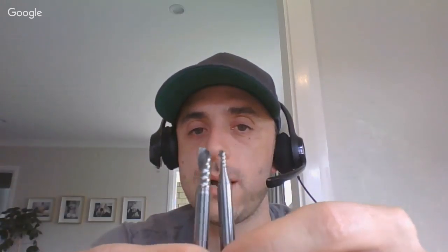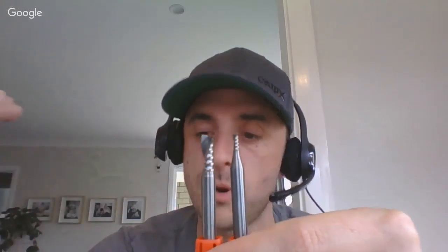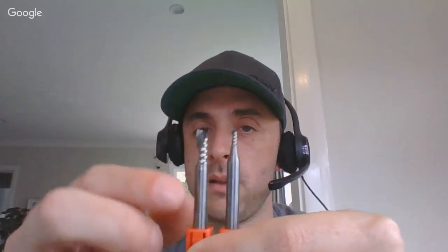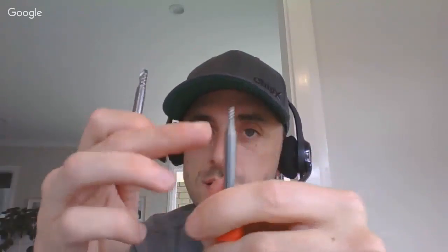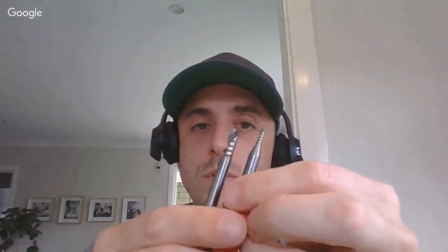But the biggest thing is that you have to spin it twice as fast. That surface speed that we talked about earlier is going to be half for a 3mm tool to what it is for a 6mm tool. Yep. So for the same surface speed, which is the efficient cutting speed as that carbide moves through the wood, this one's going to need to do twice the RPM of this one. Feed rate wise, you're probably going to have to back off the feed rate on the 3mm because, if you're really pushing things to the limit, this one's going to take a lot more abuse because it's thicker and more rigid. So that's your kind of rule of thumb.